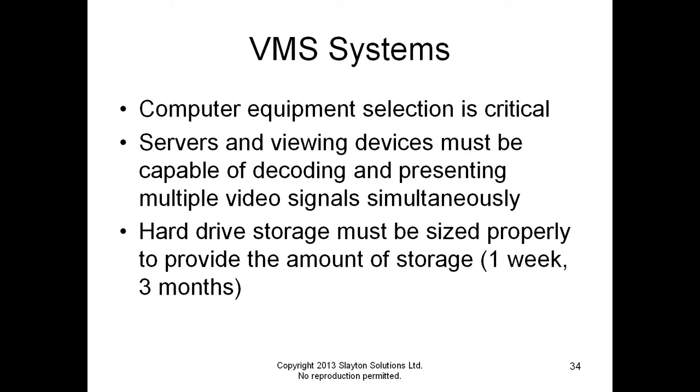It is very important that you work closely with the VMS manufacturer when they say this is the minimum PC requirements to run this particular set of software for this number of cameras, whether they're megapixel or HD cameras, and the amount of video that's coming in. All these things have to be sized up, and you have to use the PCs that they tell you to, or at least the ones that meet the minimum requirements, or else it won't work.